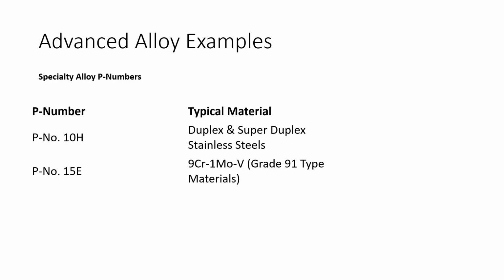They use it on power plant piping, like steam lines. So instead of having, let's say, a 4-inch wall piece of steam line, you weld it with this stuff and you might get an inch and a half or whatever. You save a lot of material, but it is some cranky, miserable stuff to weld because you have to preheat it to like 400 or 500 degrees, and then you let it cool down while you're welding, and then you heat it up again for some kind of hydrogen bake out.